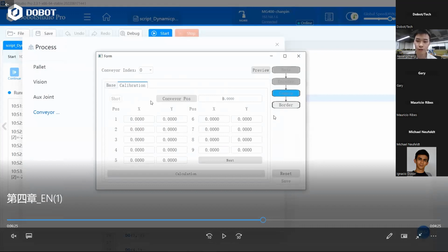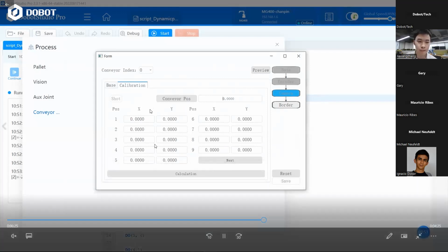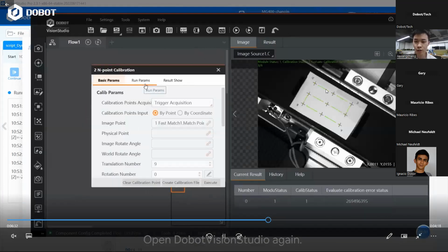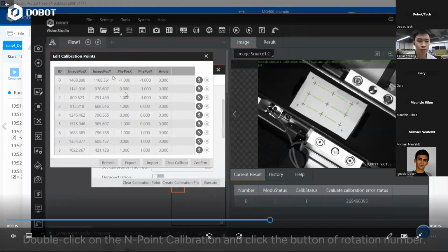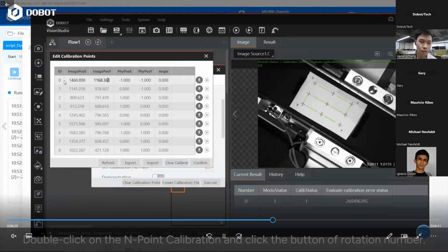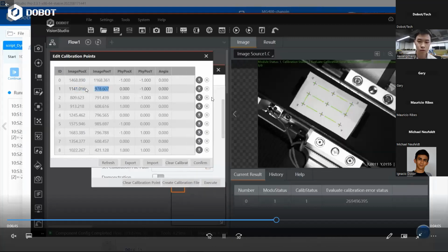After we finish the basic configurations of the camera, we'll have to match the position of the camera and the robots. So you know that we take a picture and record the 9 points, the image position of the 9 points, and we will input them by the orders.